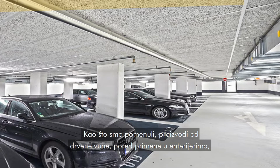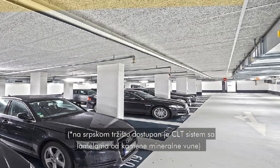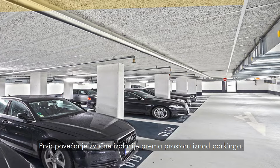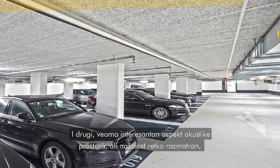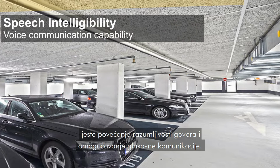As we have mentioned, the wood wool products, apart from using them in the interiors because they look so good, one of their typical applications is to the ceiling of underground parkings. And the reason for this particular application is actually twofold. First, to increase the sound insulation to the space located above the parking. And second, which is a very interesting aspect of room acoustics, but unfortunately very rarely discussed and often neglected, is to increase the speech intelligibility and enable the voice communication capability.